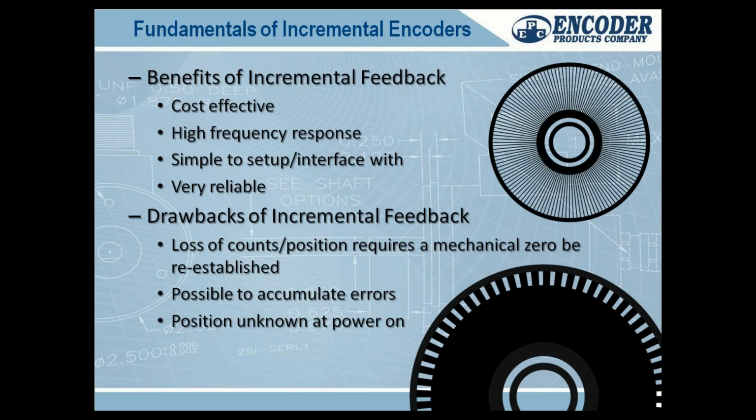Even, which we're not in this world, but if you look at the rotary scales that are out there that have 4 million points in a circle for a rotary table where you're positioning to, you know, 3 or 5 micron, inside, they're incremental encoders. They're just lines on a disk.